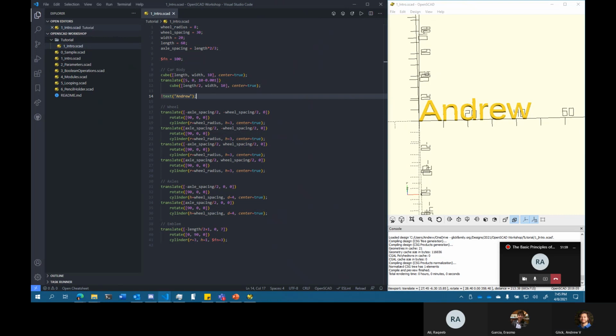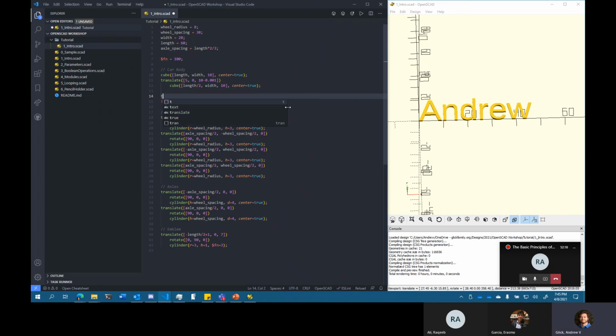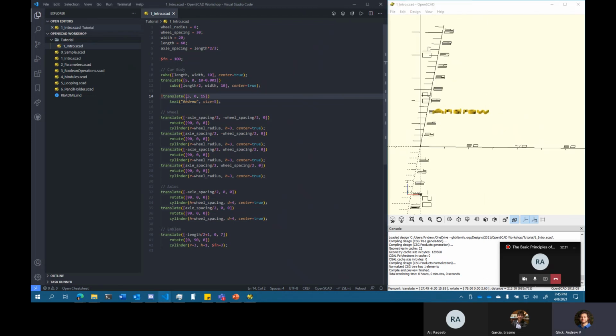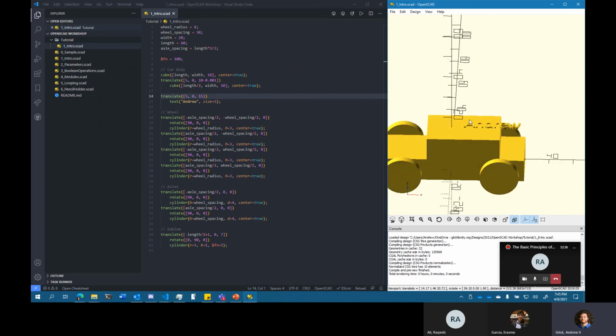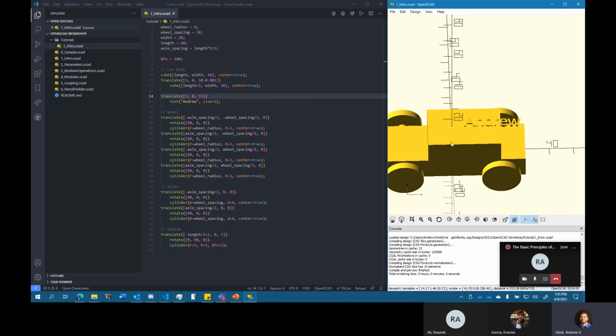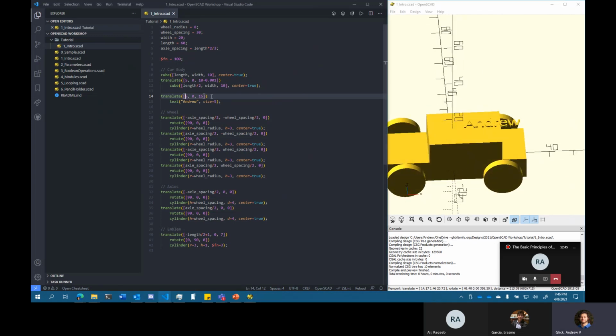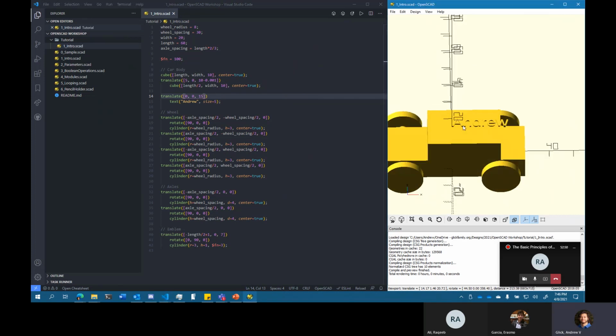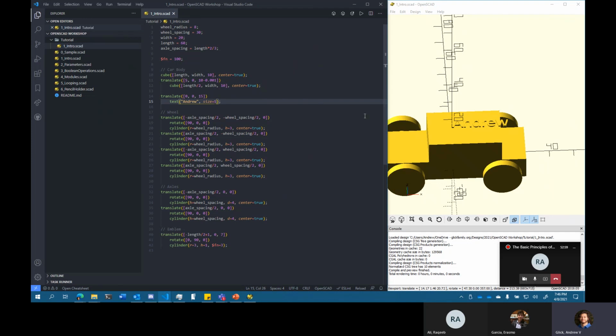Yeah, let's get back to it. Okay. So that's a little bit big for the car. We can say the size is smaller, so size equals 5, and then we can also align it with the origin. First I will translate that up. So we'll do translate 5, 0, and maybe about 15. There. That translated up, and actually we don't need the exclamation point anymore because we have the car. So this is placing the text based on the origin here, and we could probably move it with the translate. I should not have added that 5 because that's confusing. We could probably move that into place by messing around with it, but it probably wouldn't be exact, and depending on the length of your name and the width of the characters, it could change how it is centered on this piece here.